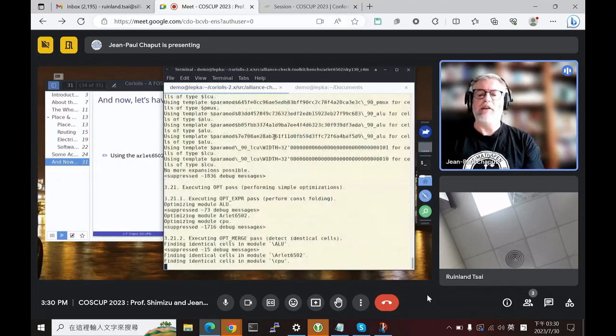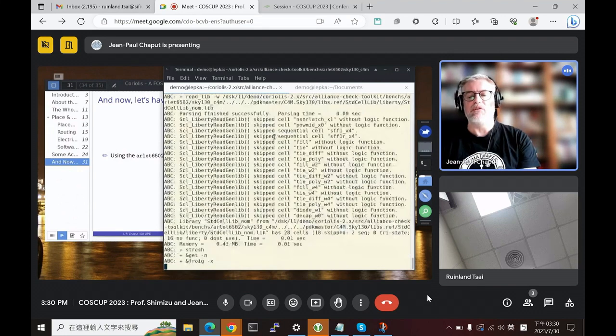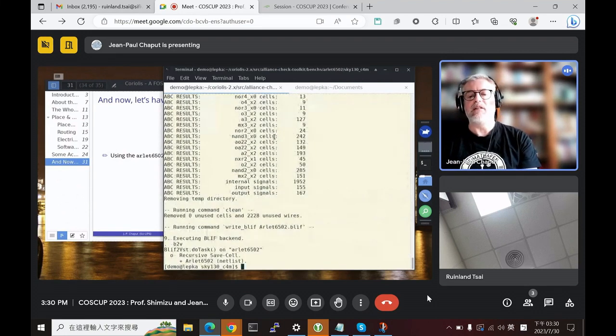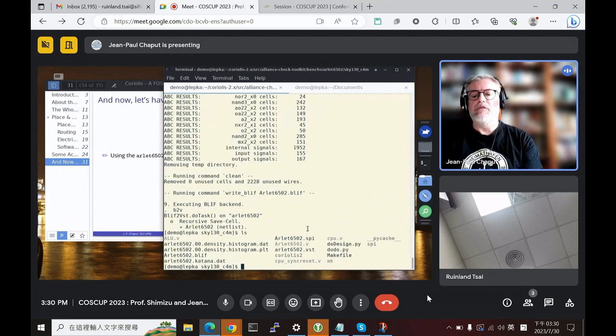In fact, we apply Yosys. For those familiar with Yosys in the FPGA world, you can recognize its output. And then you get your netlist. Here I have my netlist, which is in VST. VST is in-house. It's a degraded version of a VHDL netlist. VST stands for VHDL structural, which means in fact VHDL netlist.